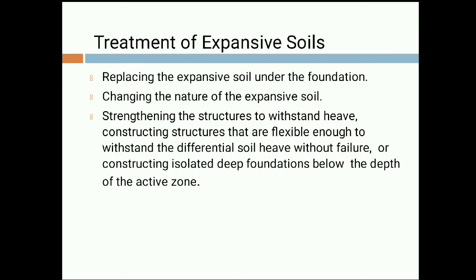Now let us see which are the different treatments which can be done on the expansive soil. First one is replacing the expansive soil under the foundation. The first solution is, if we can remove the surrounding soil around any structure, we can decrease the amount of expansion around a structure. Second one is changing the nature of the expansive soil, changing the property of the soil by mixing with some kind of cementitious material or supplementary material.